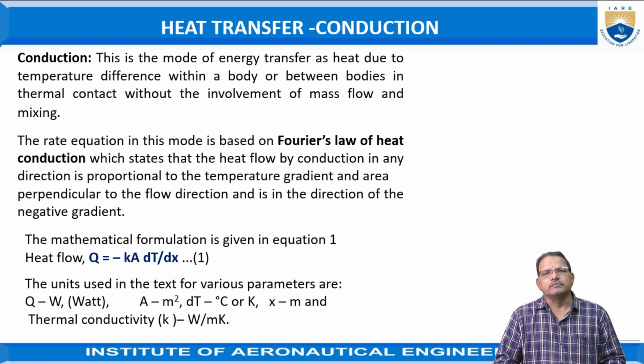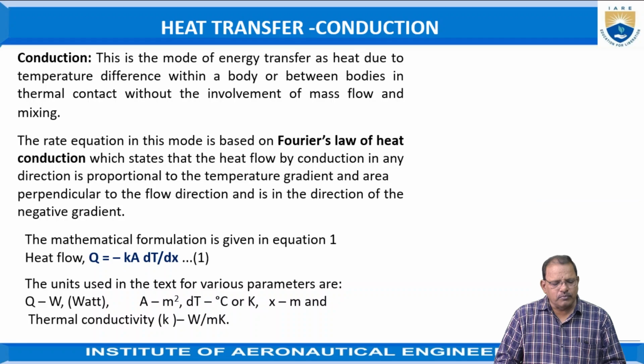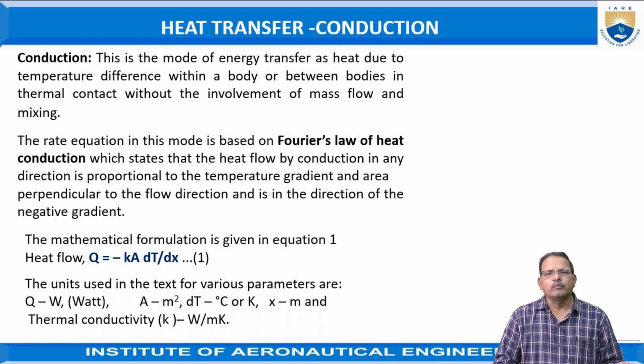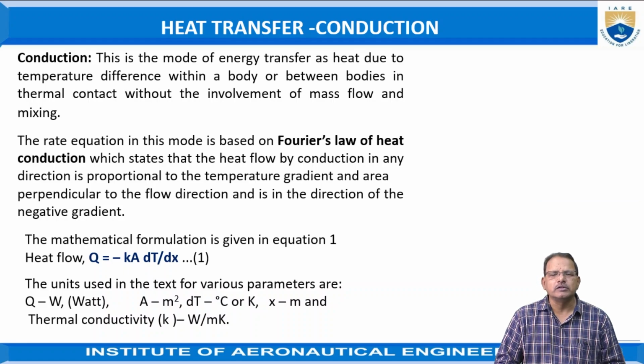Conduction is the heat transfer which takes place particularly in solids, from higher temperature to lower temperature. The amount of heat energy flowing depends upon the thermal conductivity of the material, the area of cross section, the temperature difference, and is inversely proportional to the thickness of the slab.